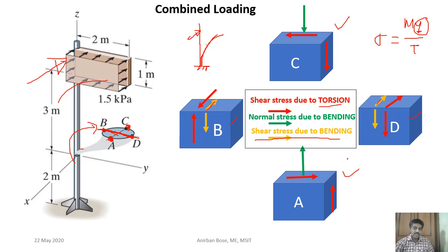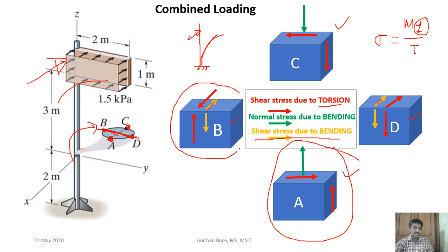So in this way different kinds of combined stresses will come in the element, and our main job from the loading is to identify these elements. This is the most important thing, to identify these stress elements. These are called the stress elements, where we show the different stresses, normal and shear stresses, on that element at different faces. Once we can identify the stress element from the loading, then we'll go to the next step.